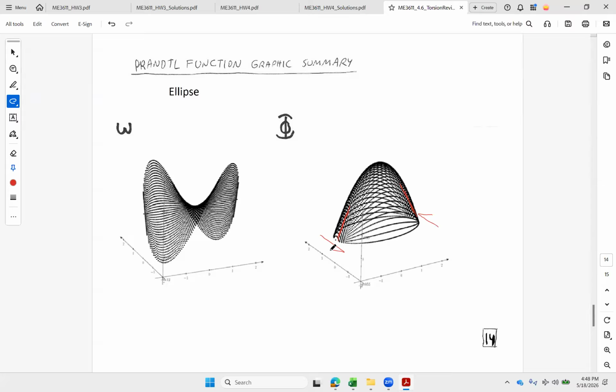Now I've got to get to the exact same point, but from two places closer together. So my slopes on the bottom and the top quadrant points are going to be higher. This is a steeper slope right here, and a steeper slope down over here on the back, because I've got a shorter distance to cover here. Here I had the same height change, but a longer distance. So I expect these blue slopes to be a little steeper, and d phi dy is a direct relation to my tau xz. So my xz stress is going to be real big, a little bit bigger than those red ones, and it's going to happen at this spot and at this spot right here.